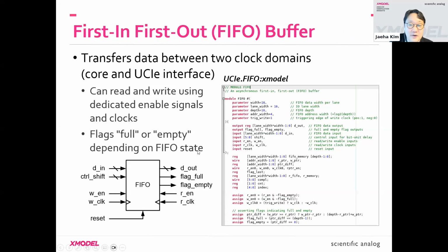Okay, so the FIFO is nothing special. It's a Verilog block that implements a buffer-based FIFO. On the left, you have a set of signals that control writing. When the write is enabled at the rising edge of the clock, you write your input data into the FIFO buffer.